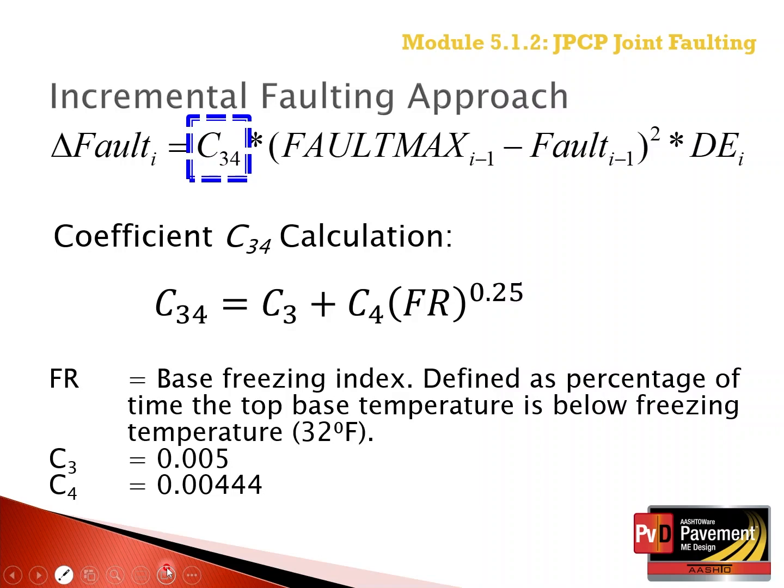For the time increments when the base temperature is always above freezing, the C3 coefficient of 0.005 and the C4 constant of 0.00444 applies to all incremental faulting computations.